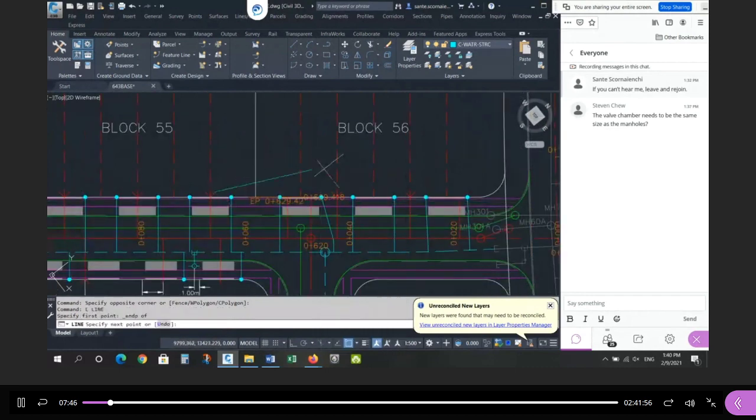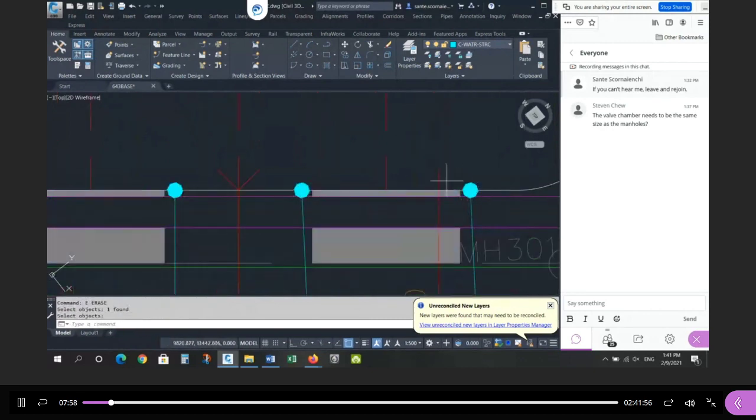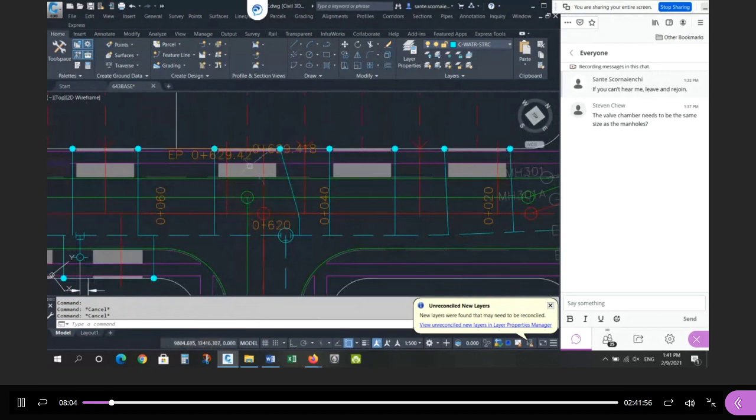The other thing I did then is stretch the pipe into the lot the same amount as the tails that you see here. Just going to extend this to this location, the single service and the single service. So it protrudes into the lot the same amount as this. Okay, so it's consistent looking. So this was a common error, right? The dual here going through the storm, don't do that. And the water service going into the chamber, don't do that either. Okay. A choice, I didn't take any marks off.